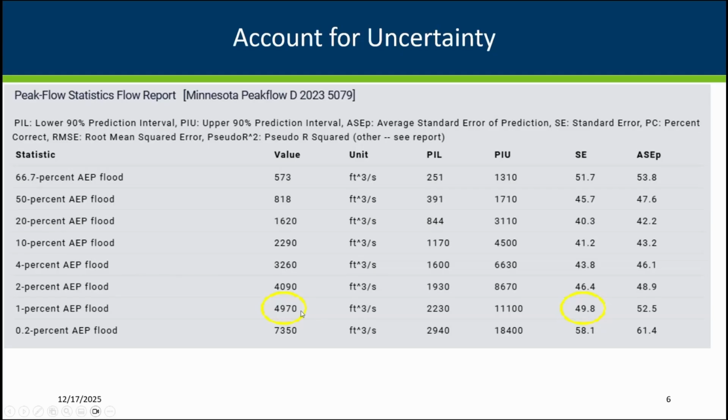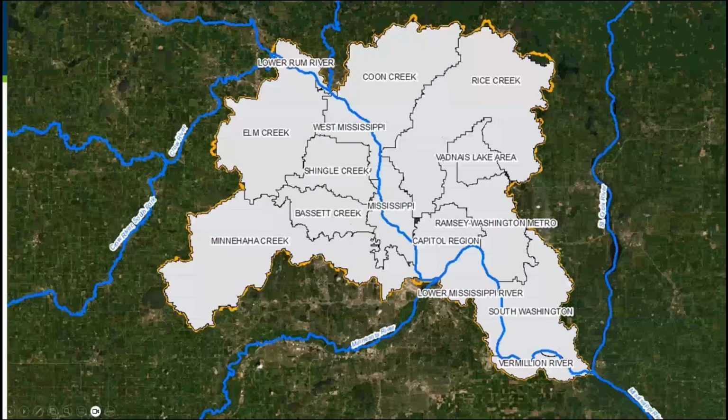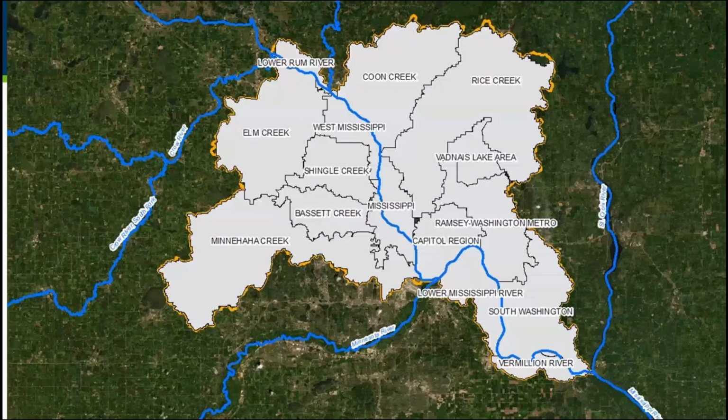So in this situation, we might be modeling and mapping based on about 5,000 CFS, but the real 100-year flow might be another 1,000 or 2,000 CFS more than that if you're using that 50% error. So that could mean a difference of whether or not somebody is mapped in or out of that binary situation. And another way the future flood risk data will incorporate some probabilistic analysis is they'll be running Monte Carlo simulations, running a storm track across a watershed.